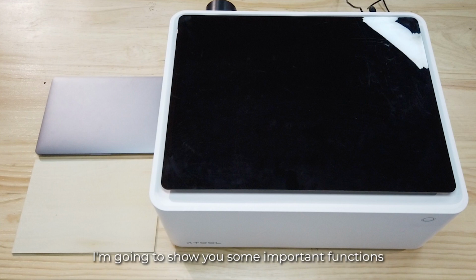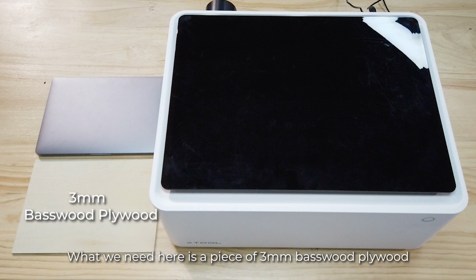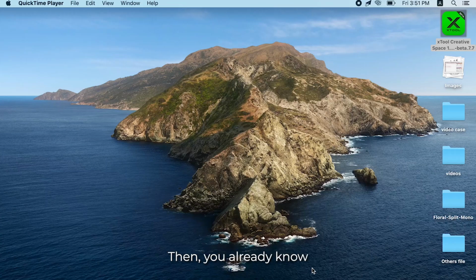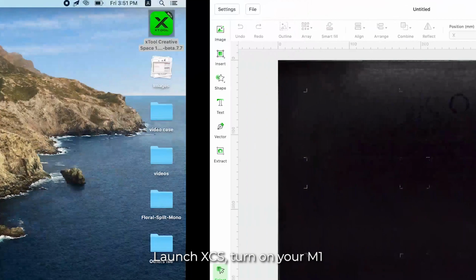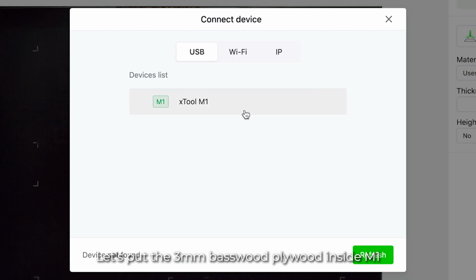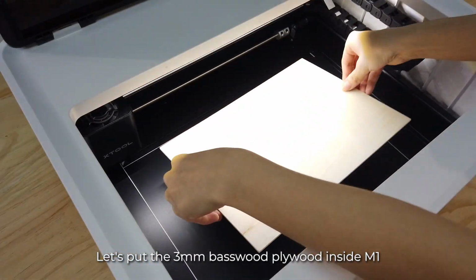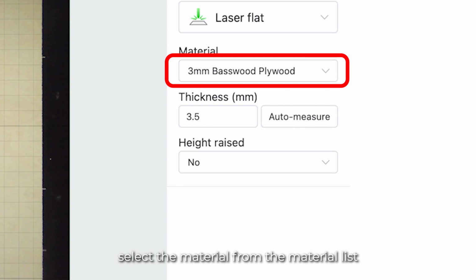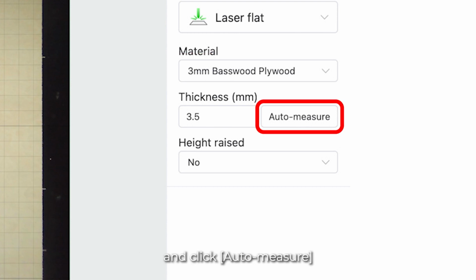Now, I'm going to show you some important functions of vector images with an example. What we need here is a piece of 3mm basswood plywood, a computer with XCS installed, and an M1 machine. Then, you already know. Launch XCS, turn on your M1, and connect them. Let's put the 3mm basswood plywood inside M1, select the material from the material list, and click Auto Measure to get the accurate thickness value.